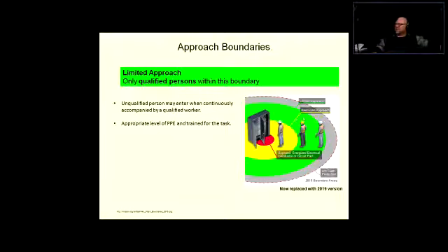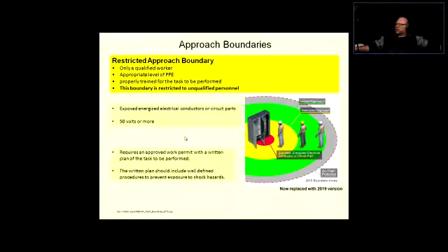Now we're moving to the green area here, right? Limited approach, only qualified persons within this boundary. Unqualified persons might enter when continuously accompanied by a qualified worker, with appropriate level PPE, and trained for the task. So you're going to have a little bit of a briefing of what you can do, what you can't do when you are this close to the energy source. All right, now yellow.